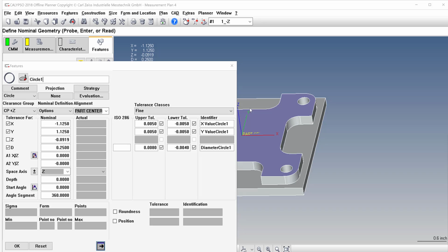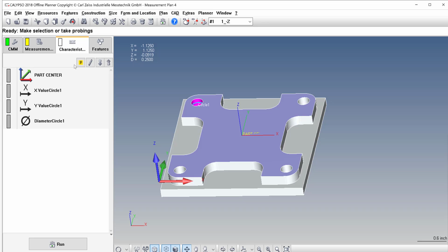If you put a Y positive on the workpiece with a Sharpie, whatever needs to happen to tell whoever what circle is out, then they would need to remember that, if they're on a CNC machine, what they did. But as far as an inspection standpoint, that's none of our business. So we're good here. And this is what we're going to kick out. We updated the alignment, and we're kicking out characteristics for the X, Y, and diameter. So we'll hit OK. So now circle 1 is taken care of, okay?